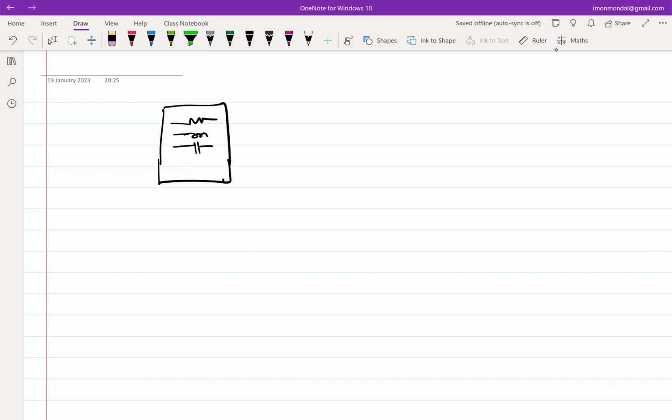I also have a doubt. There's some component, and I is the current into it. Can you still apply Thevenin's theorem? You can apply Thevenin's theorem everywhere, as long as it is linear. And even the steady state thing is not particularly valid. We'll see why. Normally, in the questions that we attack, we say steady state because it's easier to solve. But Thevenin's theorem doesn't really matter whether the circuit is in steady state or not, as long as it is linear. Okay, let's go through the proof.